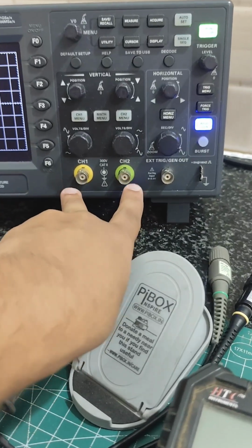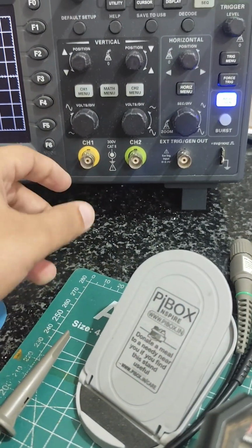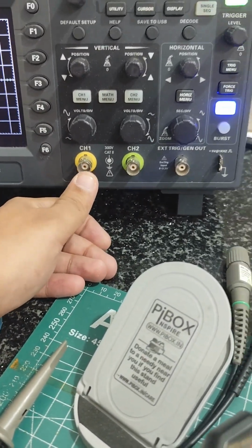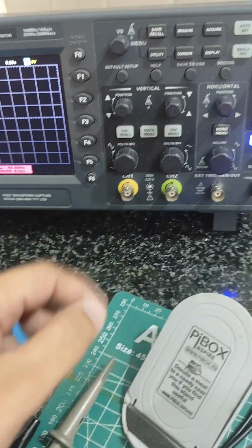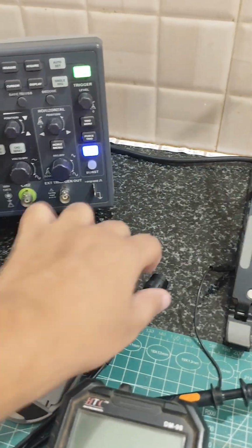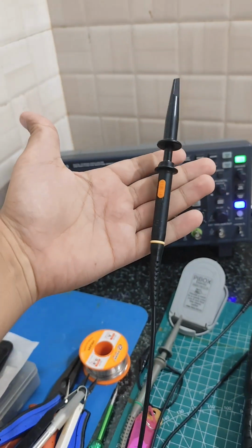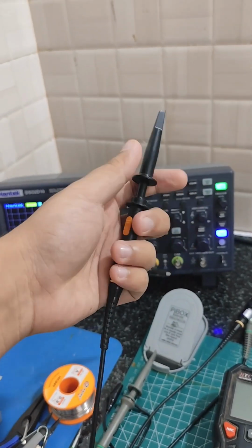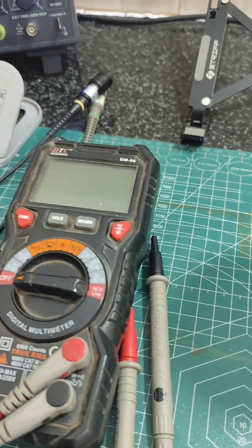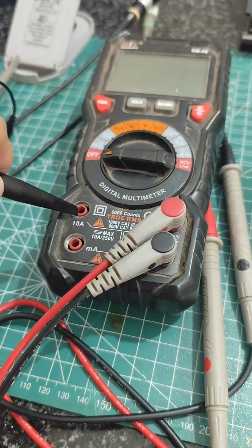These connectors are known as BNC connectors. There's a grounding outlet here, and inside this the main signal goes through. And we cannot just connect any wire and check the waveform here. It doesn't work like that. With this we have to use what we call probes. So a probe looks like this. We have a switch here, and a clamp like this, so we can clamp a wire or something like this. It can grab onto it.